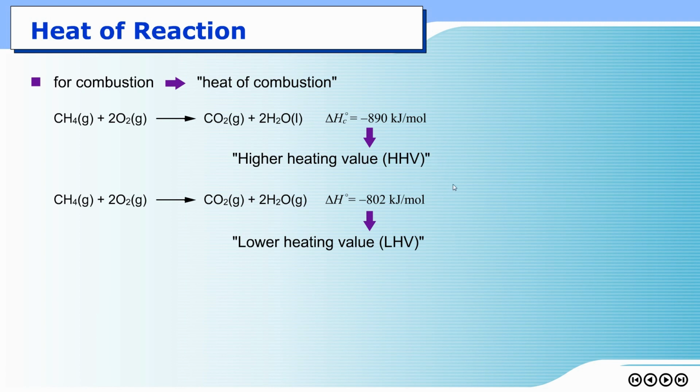The difference between these two is that for actual application, for calculating the amount of energy released from combustion, we would use LHV, because conventionally after combustion water stays as vapor, since the temperature is high enough to evaporate water. HHV is used as a limit. It tells you the highest energy that this fuel can produce.